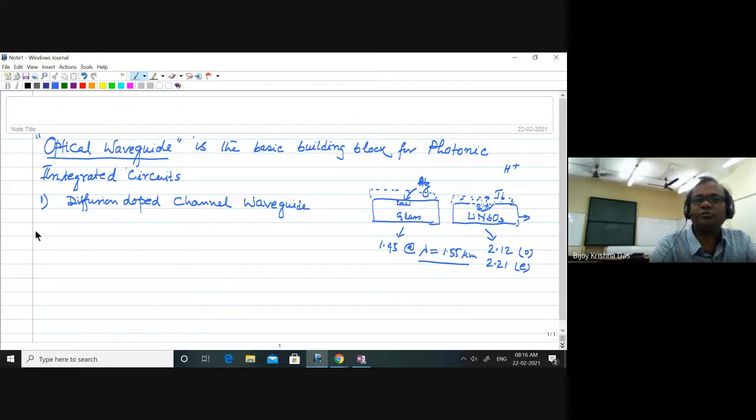Their refractive index is also close to 3.5. So those are the highest possible refractive indices we can consider as a core for optical waveguide design. And if you find, or maybe synthesize, some material having a refractive index of probably 5, 6, 7, so most welcome. To my knowledge, silicon, gallium arsenide, or indium phosphide have the highest possible refractive index available for waveguide design. Is that clear? Okay.